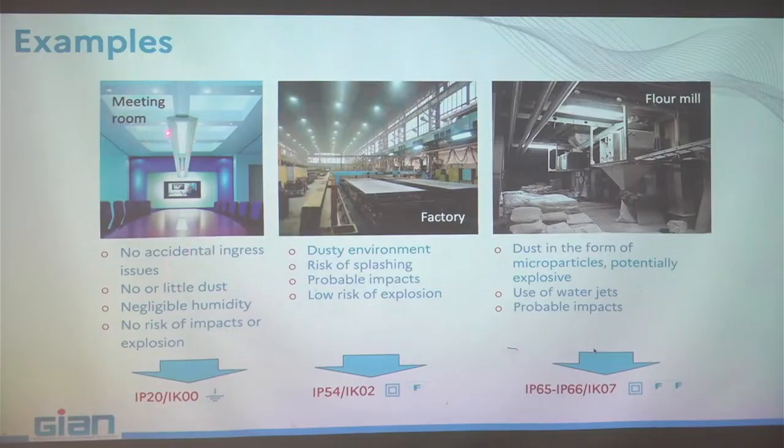To touch the luminaire, you have to get on the table, which is intentional. Negligible humidity, no risk of impacts, no explosion, no fire. In that case, IP20 is fairly enough. IK00 is okay also, and just connected to the ground. Class 1 for the electrical hazard is enough.